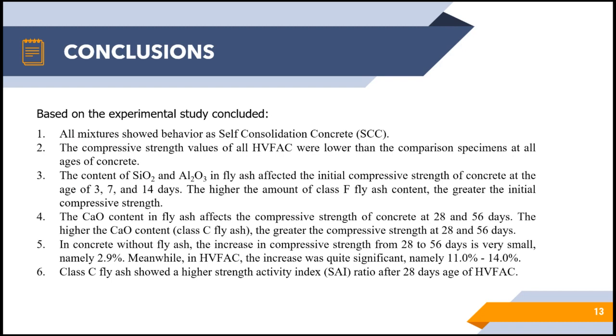Second, the compressive strength values of all high volume fly ash concrete were lower than the compressive strength of the specimen of all normal concrete. The third, the content of CaO, SiO2 and Al2O3 in fly ash affected the initial compressive strength of concrete at the age of 3, 7, and 14 days.